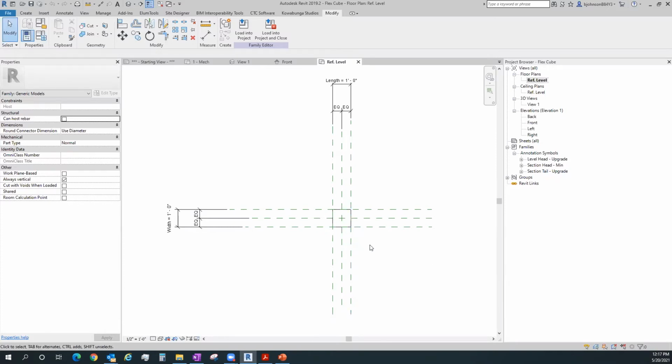So then I could attach that to a floor, a vertical face or a ceiling or a roof or something like that as well. I wouldn't typically go beyond that with the placeholder family to specifically a wall-based or a ceiling-based or something like that, unless I knew that I also had to cut holes in the ceiling or the wall objects. In those cases, that would be the only other reason to generate another family type like that. So if it was an object that penetrates a wall, such as a hole for a damper or something like that, maybe I would generate that as a wall-based object and then use a void object inside the family to give me exactly what I wanted in that case.